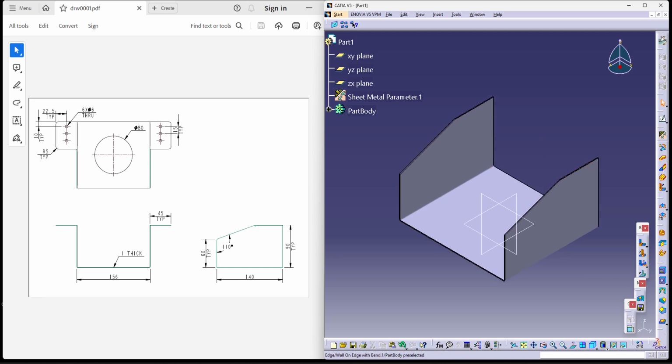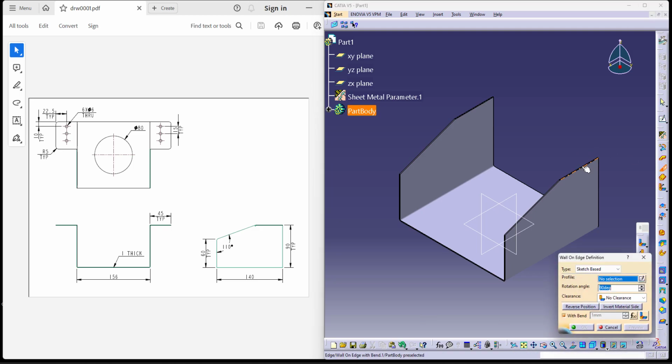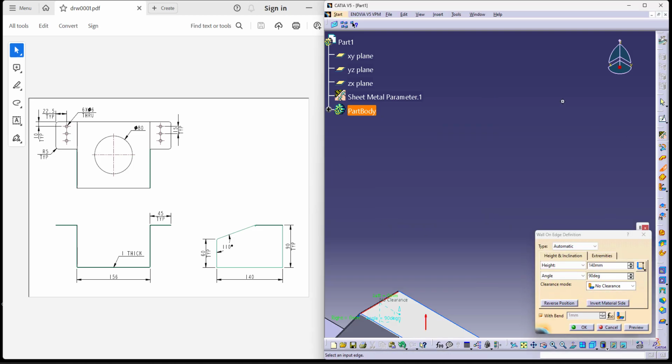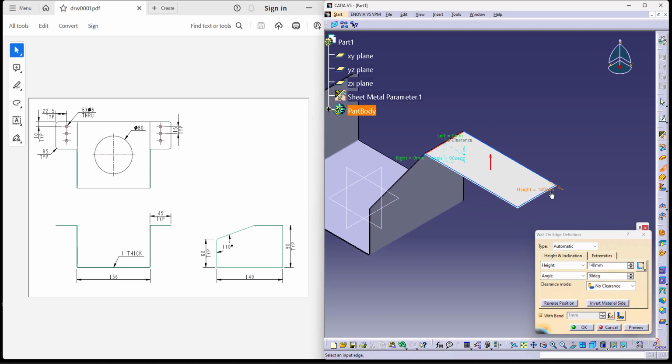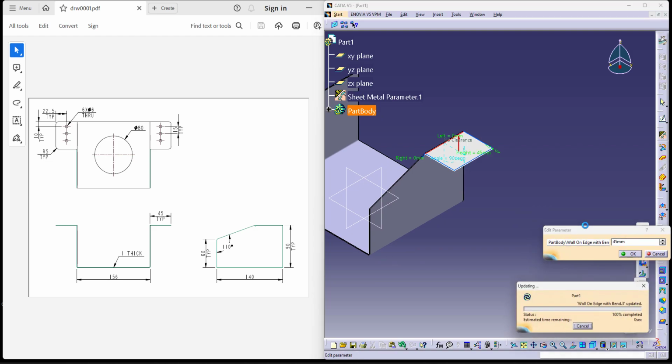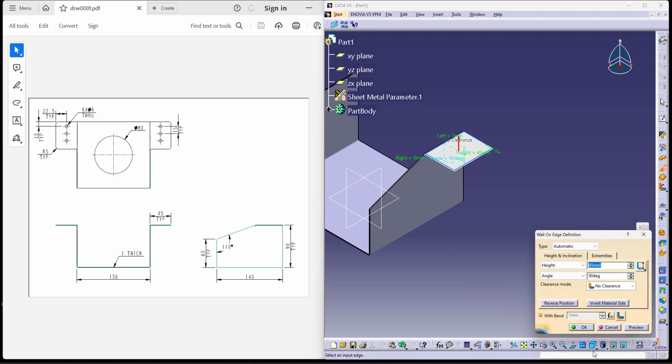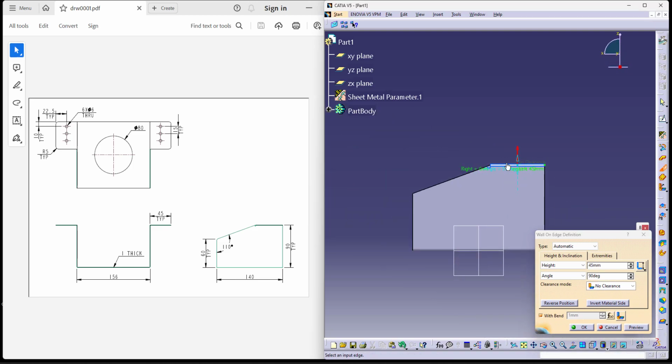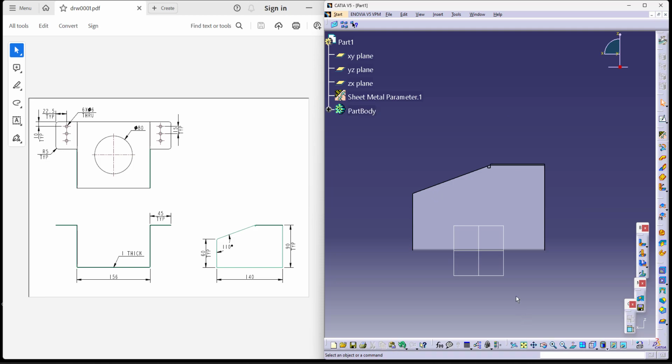Now there are two more walls, as you can see over here, which is the overall distance is actually 45. So I'll simply use the wall approach again and then try to do it. This is a normal wall because since it's a rectangle wall, I don't have to take much effort to make a shape or anything. All I have to give is the overall length of the wall. Now, when I go into the right view, you can see that it auto takes the relief which we have already given earlier. Let me just try to say OK and show it to you.